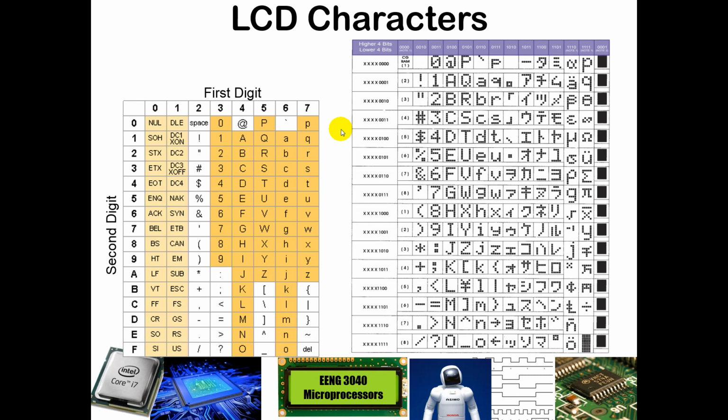So for example, 0 is 30 hexadecimal. So this represents the first hexadecimal digit, this represents the last hexadecimal digit. So if you wanted to write a displayable 0 out, then you would send in 30 hex. If you wanted to send the letter capital R here, you would send 62 hexadecimal. As you can see over here, this even expands to put out various Asian characters. You have some special symbols like the cent symbol and things like that. This we'll use later when we get into a temperature lab for the degree symbol. And so we also have some of these mathematics symbols available as well.